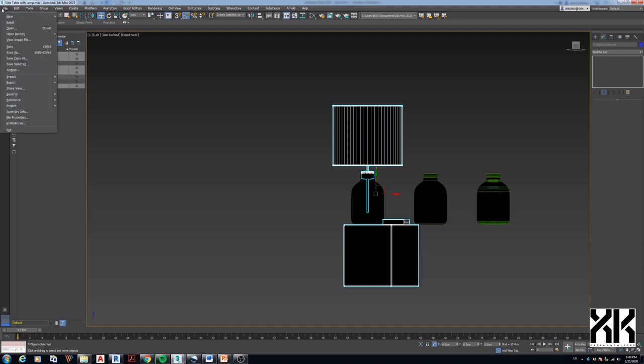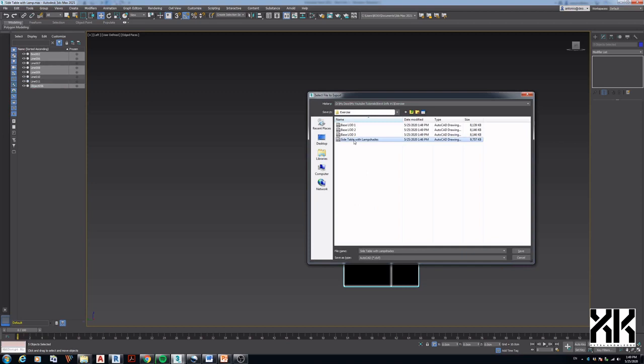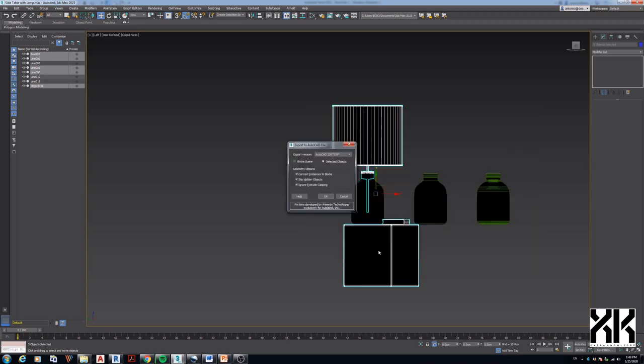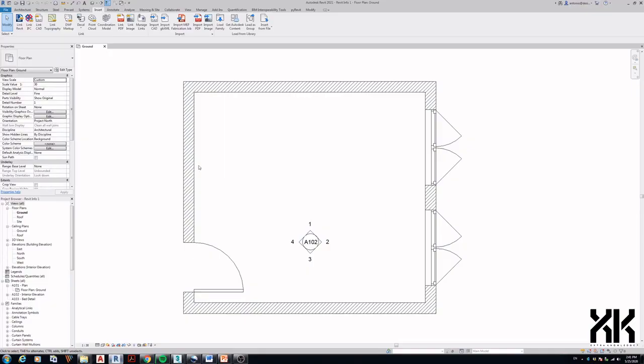And finally, export the other models at once, except the bases, and name it Side Tables and Lampshades. Now you know how to use the Pro Optimizer and the Edit Mesh modifiers. Later, we will use the Multires modifier in our second example.